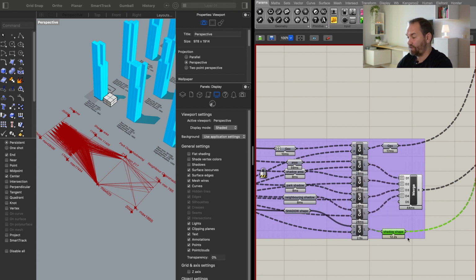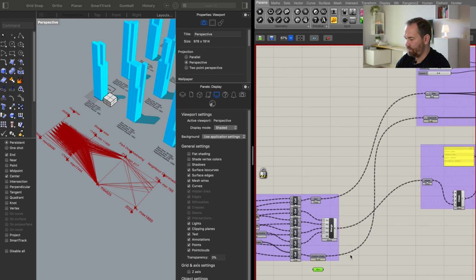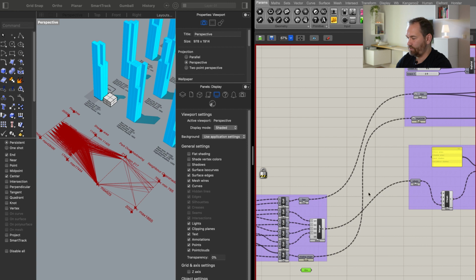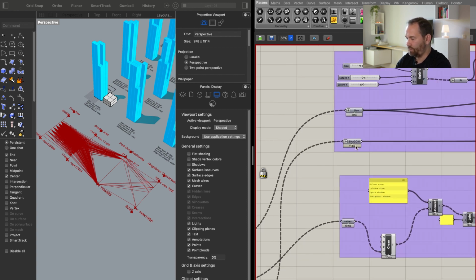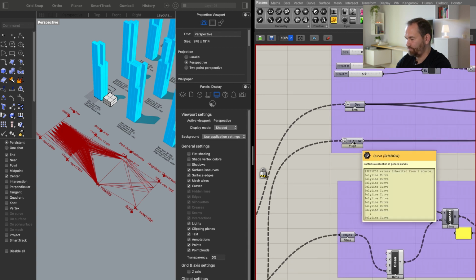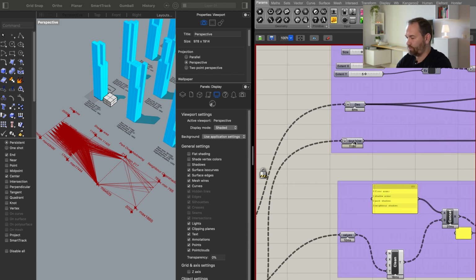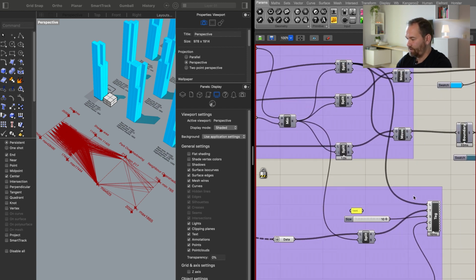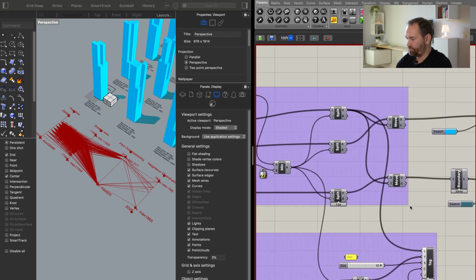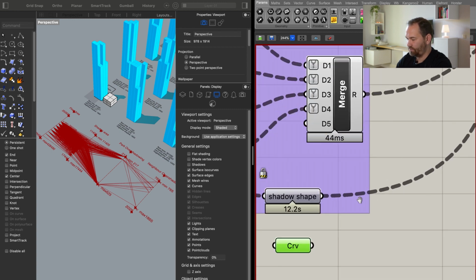So if we pass a curve again, maybe that conversion would not need to happen, and that could speed this up. So let's mark this for later. I don't want to connect anything. I have the lock of the solver on, because if I reconnect everything else after that wire will lose the profiler values. Okay, again here we see that conversion back from geometry to a curve, another 12 seconds lost. So that would definitely fix this. And that's it. Basically these are the weak spots, so that curve here.